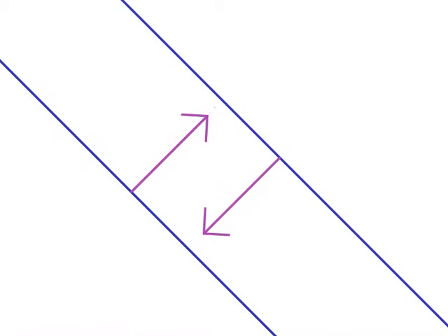The maneuvers will need to be performed for 4 headings. The 4 headings depend on the headings of survey and tie lines. 2 compensation headings must be parallel to the survey lines, and 2 headings must be parallel to the tie lines. Parallel lines must go in opposite directions. The shape of the flight path should be close to a square.